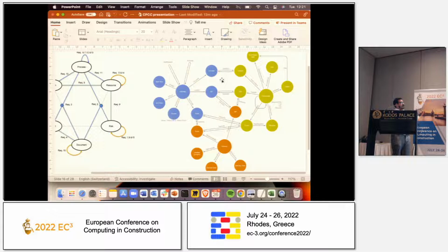So we need not actually create an Excel sheet with everything in every row. All we need is, if there is an activity, we need to have a work package and a place and a trade contractor. Then it will all find itself. The same goes for deliveries on the construction site and the delivery schedule. The same for all the documents. If a document has a work package and a location and a trade contractor, it will find itself based on the dates that we have.